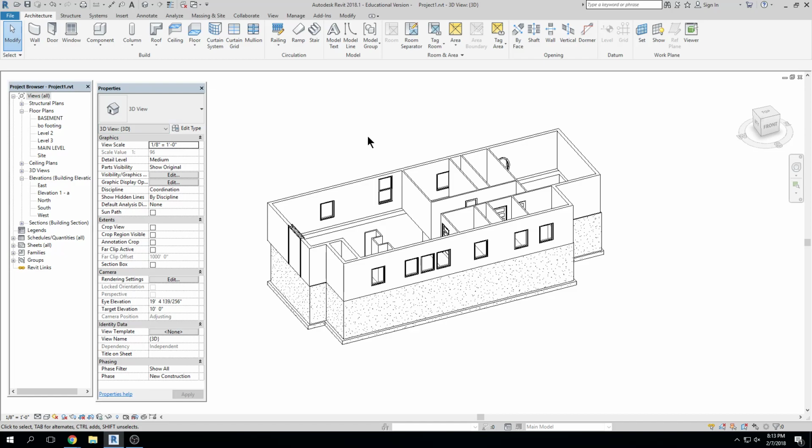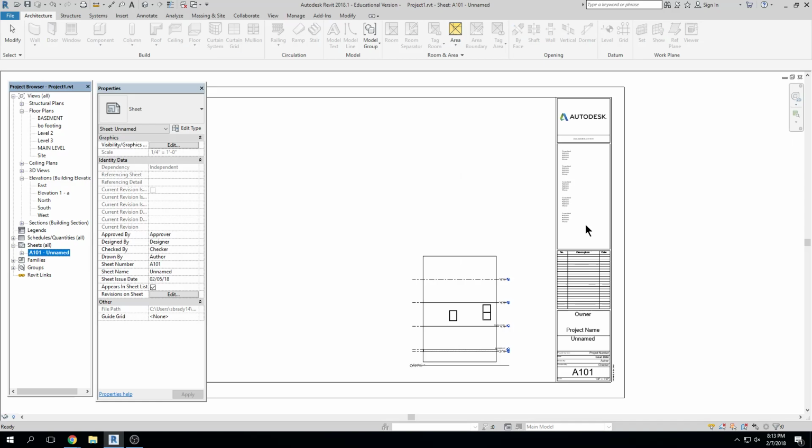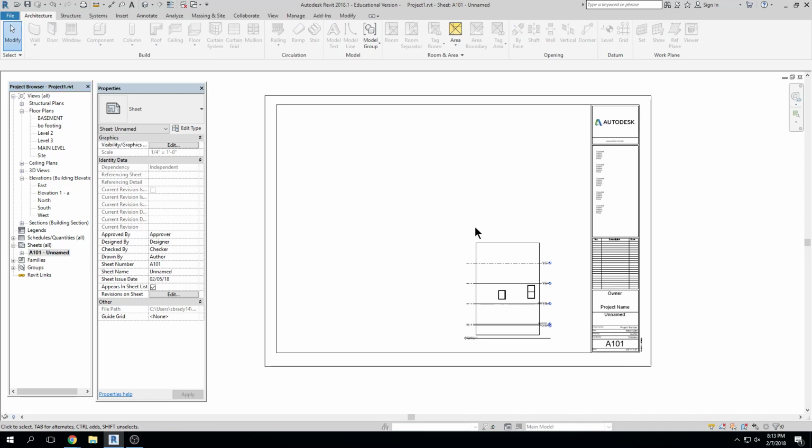Do you guys understand when I say the term sheet as opposed to the term drawing? Does that make sense to everyone? Okay. So the term sheet is something that you print, and it has specific work on it that has to do with a specific item in the drawing set. So for example, you might have a drawing of a ceiling or a floor plan, right? But there are different types of floor plans. You have the finished floor plan, the dimension floor plan, the regular general floor plan, the egress floor plan for code review, right? So you have one floor plan that you use to create a lot of different things.